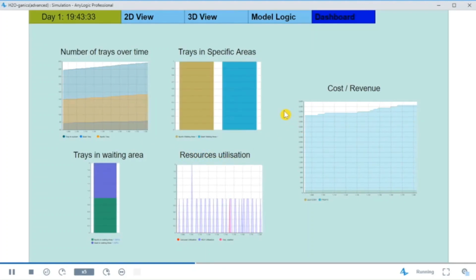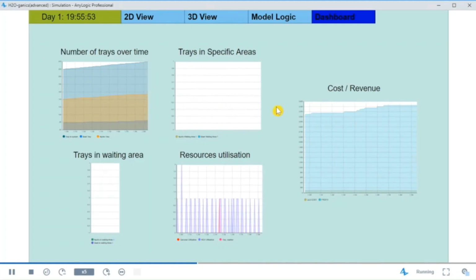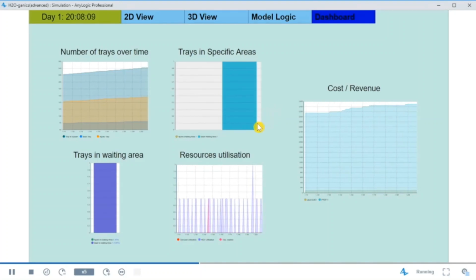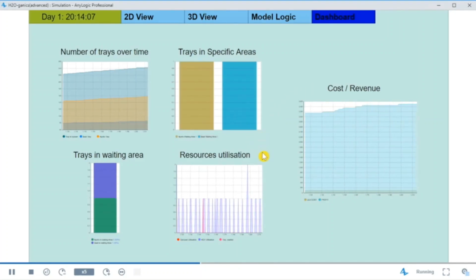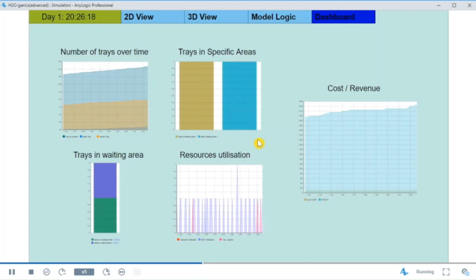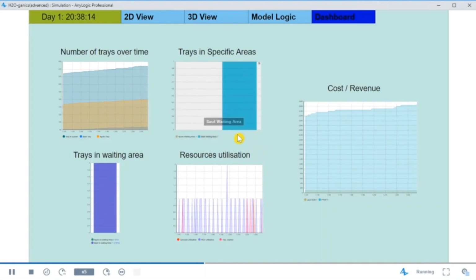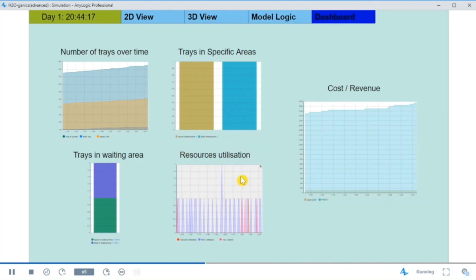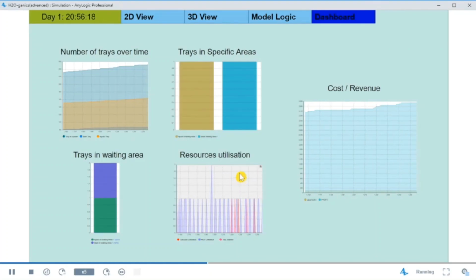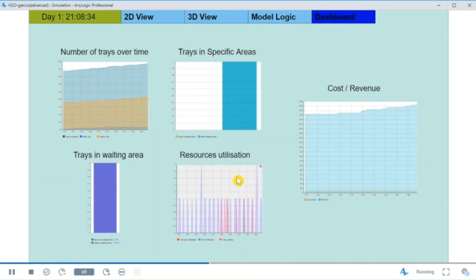Bear in mind that in most of these situations, especially for the validation and verification process, you might run a different experiment instead of this plain one. In a Monte Carlo run, for example, multiple instances of the model will run in parallel, and you can actually export the raw data to the pre-built AnyLogic database or an Excel file. I personally prefer an Excel file, as you can easily format the data to whatever style you want.